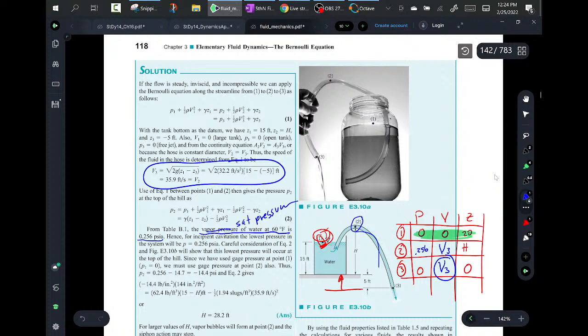First, you write Bernoulli's equation from here to here to answer the question, what is that? Once you figure that out, you copy it to here. Then I would write Bernoulli's equation between here and here, although it doesn't really matter because you already know the constant is going to be 20 times the gamma. Then you're solving for H.